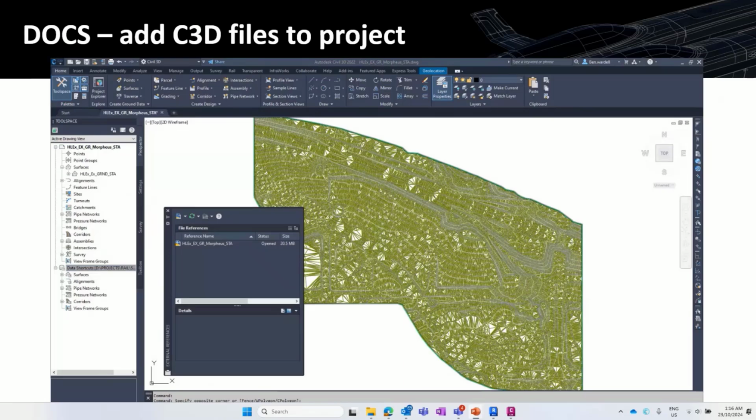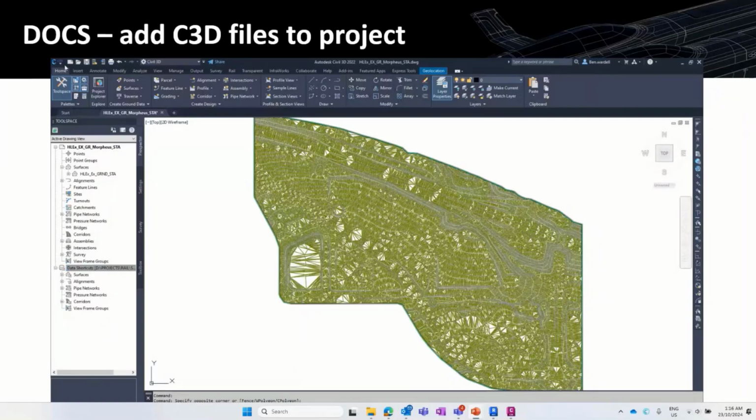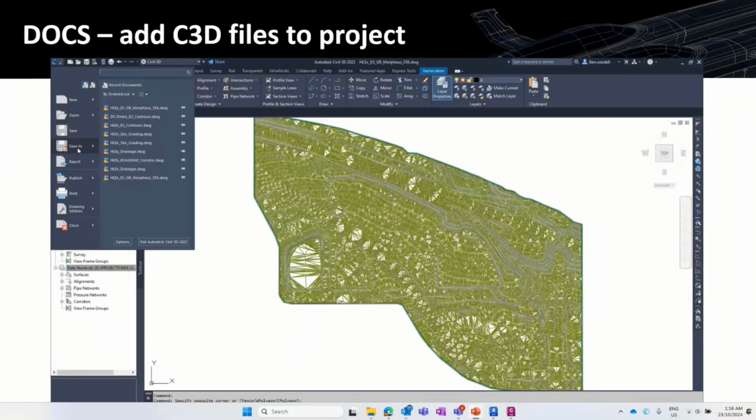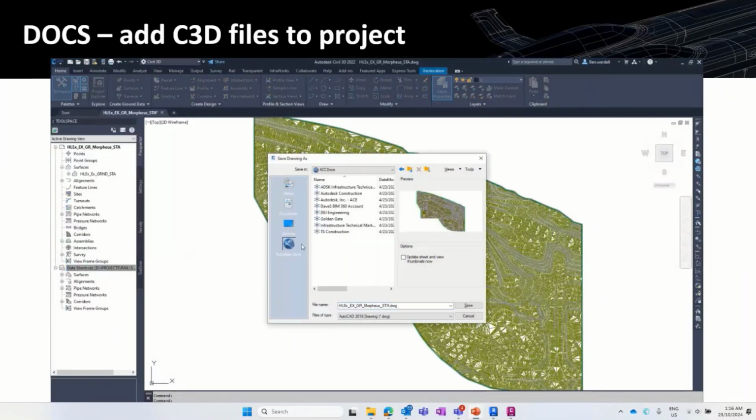This data shortcut I will explain to you later on. It is actually for you to work with all the files that you have in the ACC platform. Because when you want to draw, of course you want to have multiple AutoCAD files or a Civil3D file that you want to refer to. So you can set that up in data shortcut.